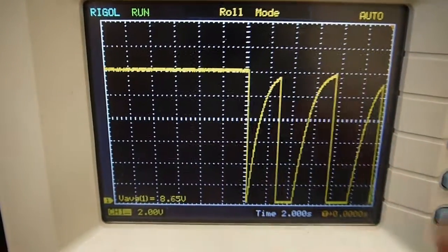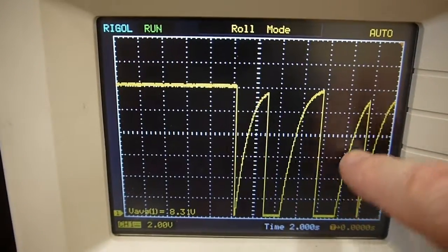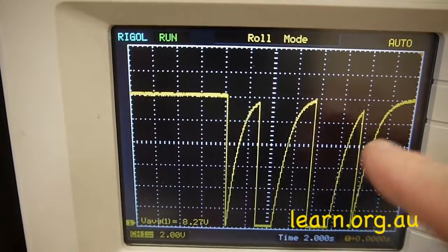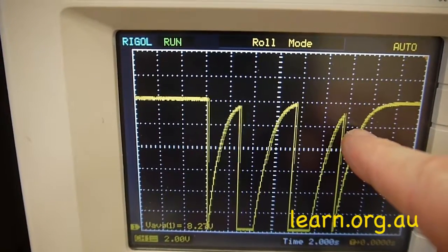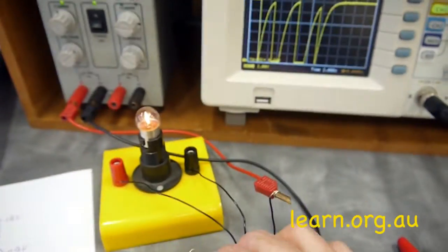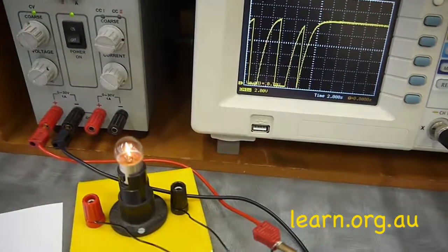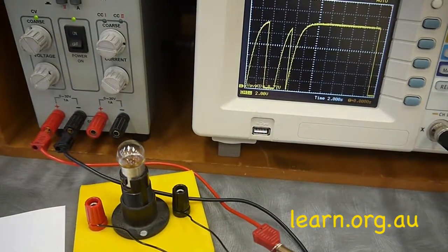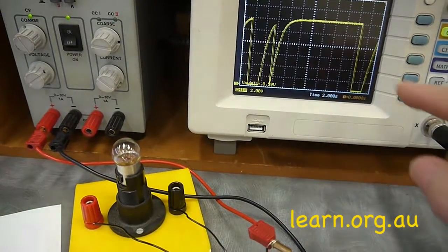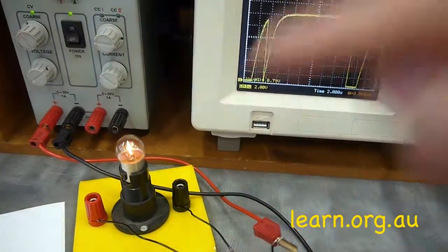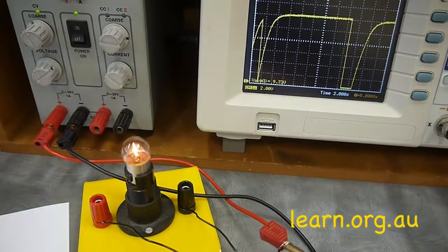I'll do that, and we'll see it on the oscilloscope, shorting it out, opening it. And when it opens, we've got the charging taking place here. And we need 10 volts, that's going to be about here, before that lamp illuminates. So I'll hold the camera back a little bit, and I'll short circuit that capacitor, and okay, go. Here's the charging taking place. Note where the light just turned on. I'll do that again.